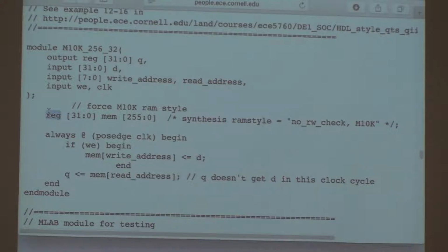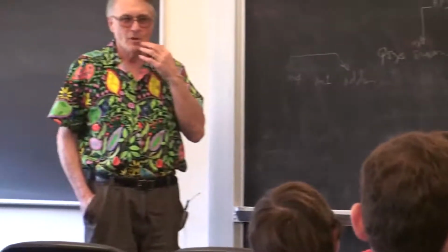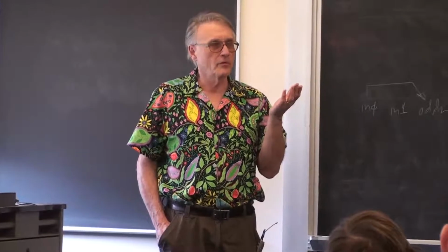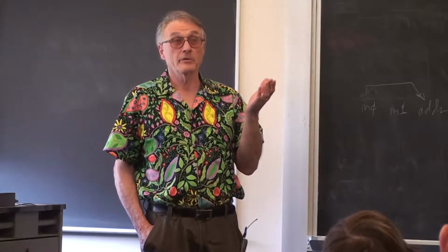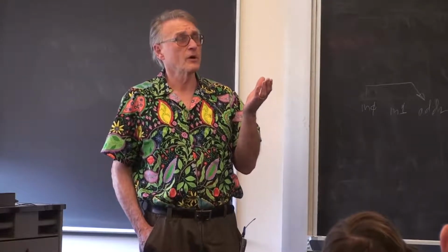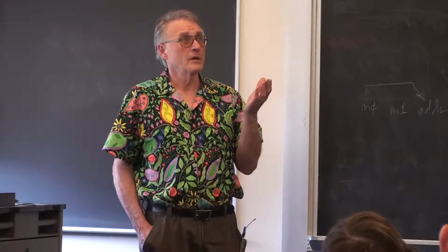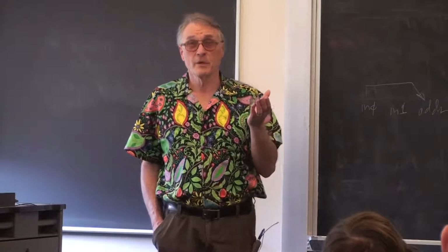So the question occurs, could you actually render the Mandelbrot set into M10K blocks? You need 302,000 bits. There's 4,400 on-chip memory bits.